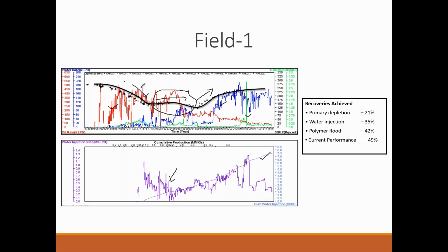if I try to draw a line, this is the initiation of the water injection. From this point we started water injection, and you can see there is a response. There is some response time. Even though I have initiated water injection, there is a decline in the pressure. So some response time is required for the pressure effect to be felt.